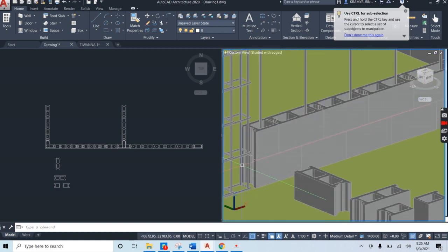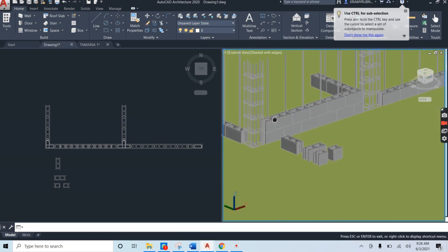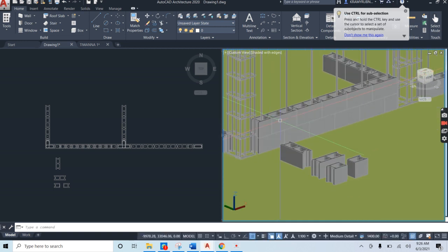And to explain what I'm saying, our third row would now have to start with a complete block, and it is done like that alternately. All right, so we could already lay another block and then another block going down the line, and it's going to end with a half. The next row is going to start with a half, and so on and so forth. So I hope you would have gotten that concept.